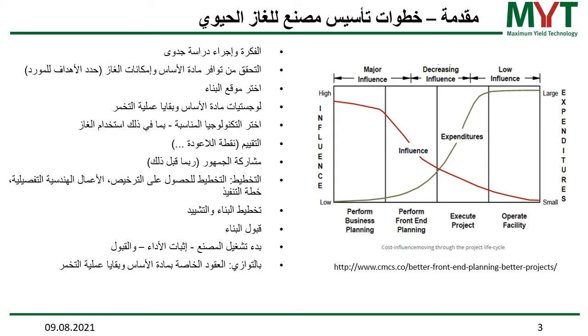Second important point is biogas plants rely on the substrates. So the characterization of the substrates, the availability of the substrates, and, a very important point, the gas potential of the substrates are very important points to check very early on. Then, of course, the construction site is a very important point to choose. Also the infrastructure, and the logistics of substrates and digestate.